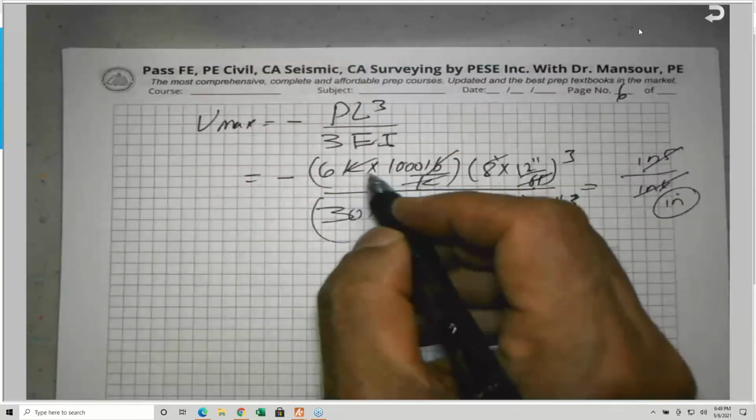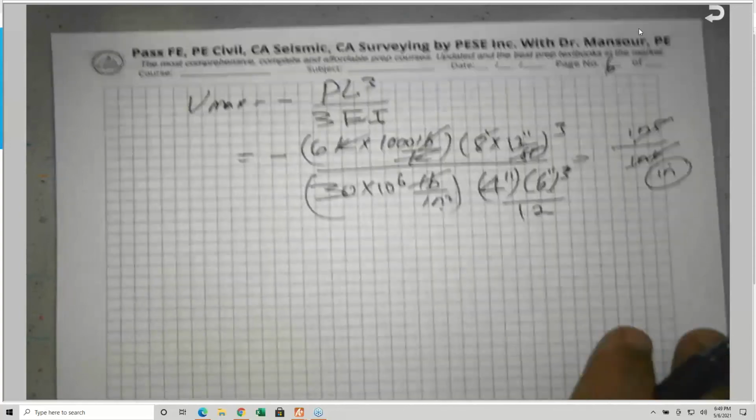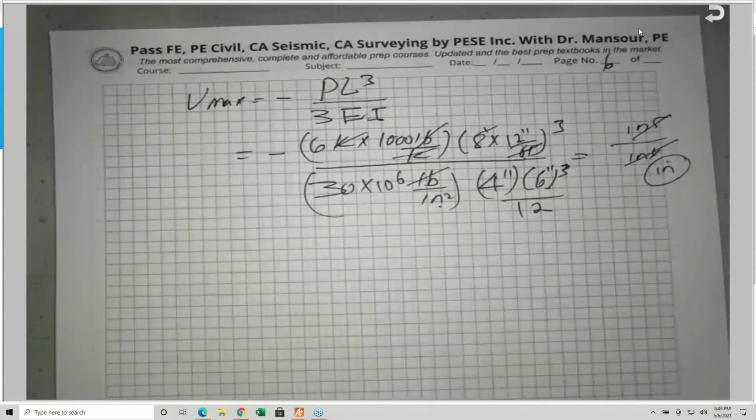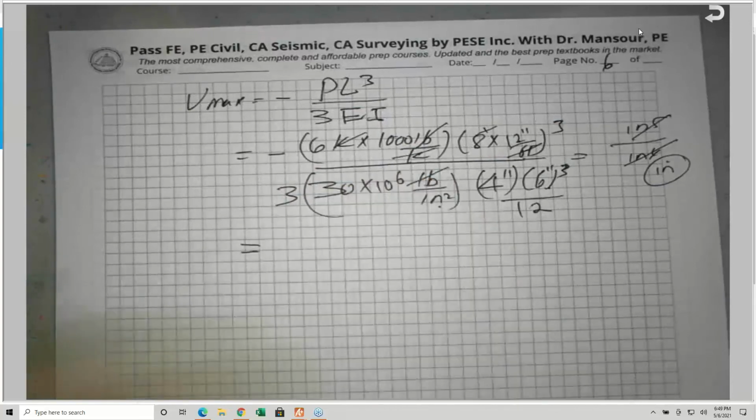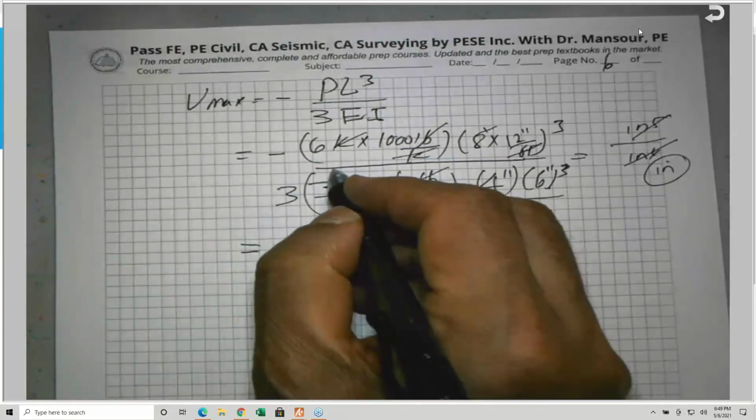And this is easy for the concentrated load. For distributed load it is a little bit tricky also. So if you do this piece of calculation, did I miss anything? Did anybody notice that I missed anything? So it'd be L cubed divided by 3. I believe I missed the 3. Okay, 3EI.